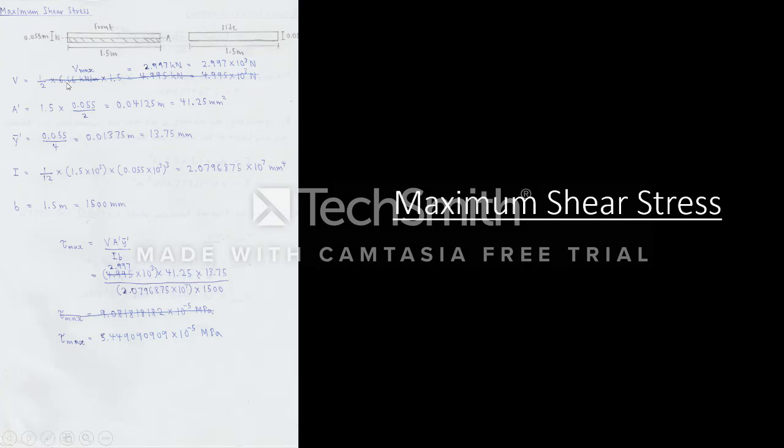Thereafter, I used the values of the maximum shear force, which is this, the partial cross-section area, which is the area of the shaded region right here, the distance y of the centroid of the shaded area from the neutral axis, which is this line in the middle, the moment of inertia value, and also the width of the cut, which is 1.5 meters, which is this distance right here. Using these values, I found out the maximum shear stress, which is this value right here.